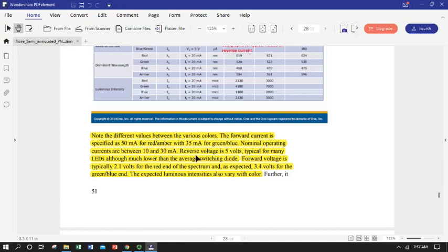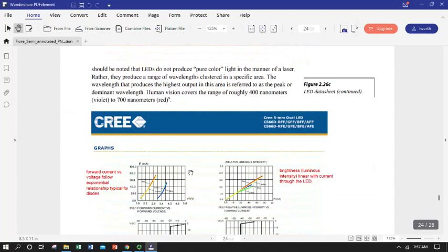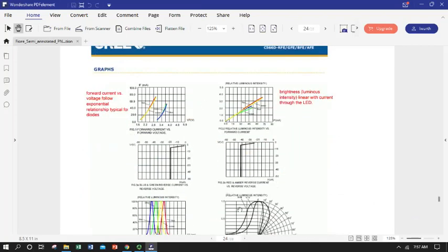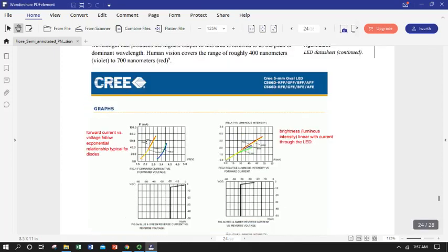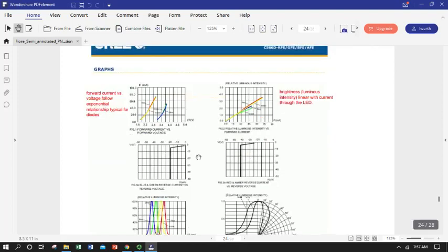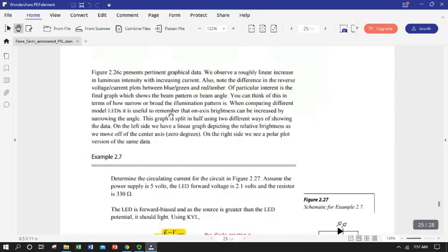Forward bias voltage differs by the color, and all of your maximum applied forward current, reverse voltage, and power dissipation can also vary by color. So that's LEDs in a nutshell. Definitely you're going to want to read your spec sheets when you're deploying an LED, because they vary quite a bit with particular composition, style, and color. If you're lucky, you'll use a set that are all produced by the same manufacturer, and you can get the electrical characteristics by color all in one spec sheet, and then maybe use a variety in your circuit.